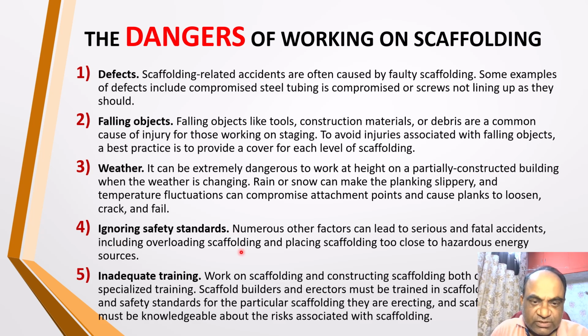Ignoring safety standards. Numerous other factors can lead to serious and fatal accidents, including overloading of the scaffolding and placing a scaffolding too close to hazardous energy sources. These two causes are very dangerous. Overloading should not be done in any case and must be avoided. Placing a scaffolding too close to hazardous energy sources is also dangerous.